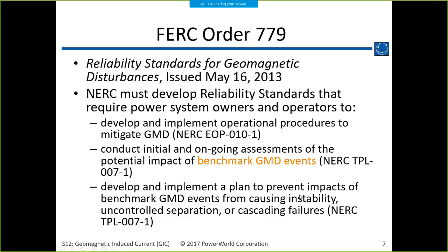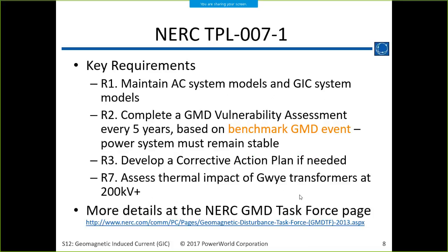So, there's basically two concerns. One is that because of the VAR losses in the transformers, you can have some instability, some voltage depression, and possibly cascading failure. And then the other concern is the heating that develops in the transformers, and whether or not that causes either an immediate failure, or if not an immediate failure, perhaps some damage that accelerates the loss of life in the transformer.